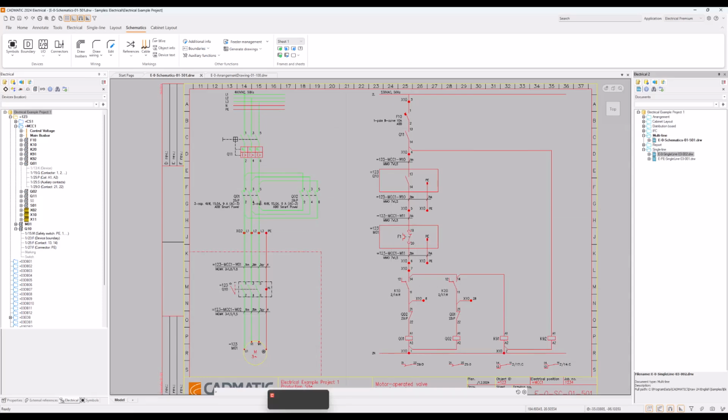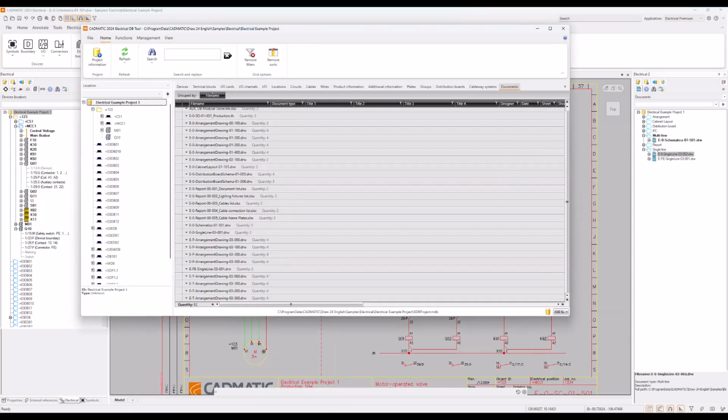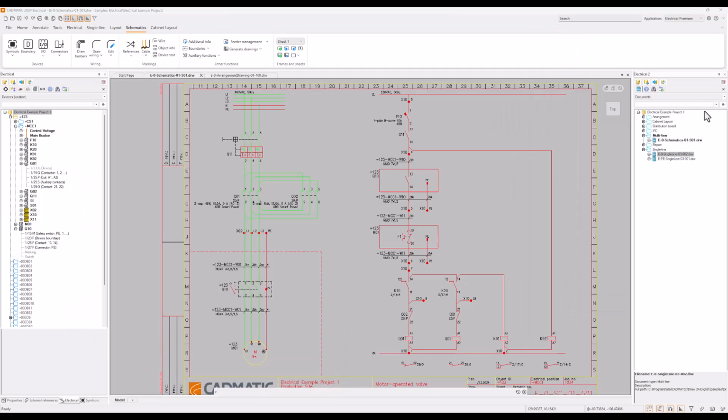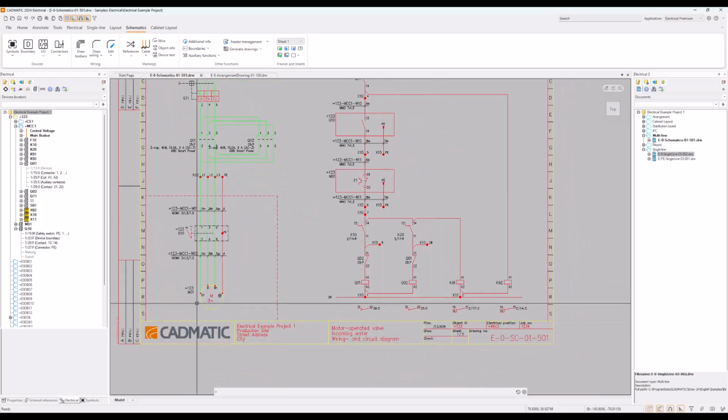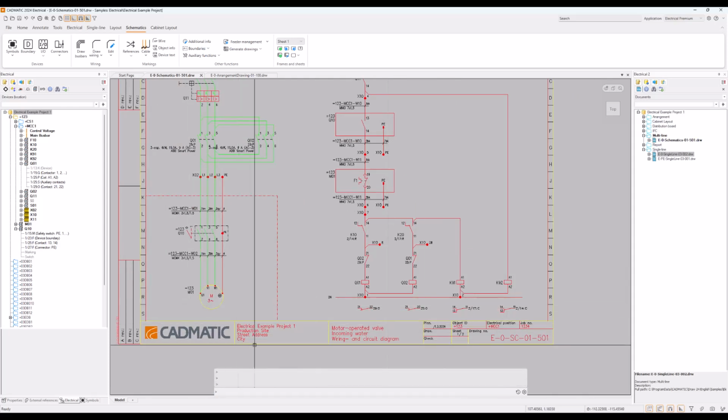So please use your database tool or the electrical project tree to change and modify your document names. Do not go to Windows directories anymore. And in case you want to edit the documents also, it applies for some labels that you can edit in the database.